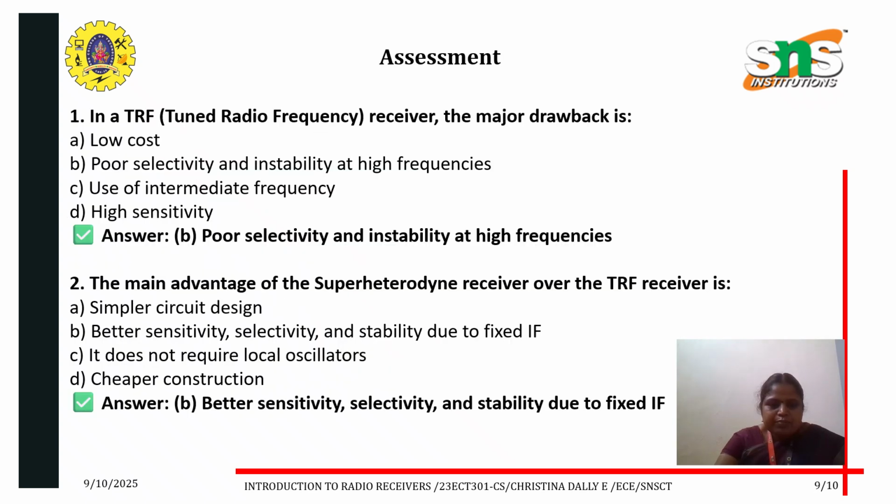These are the assessment questions. The major drawback of the tuned radio frequency receiver is poor selectivity and instability at higher frequencies. The main advantage of the superheterodyne receiver is better sensitivity, selectivity, and stability.